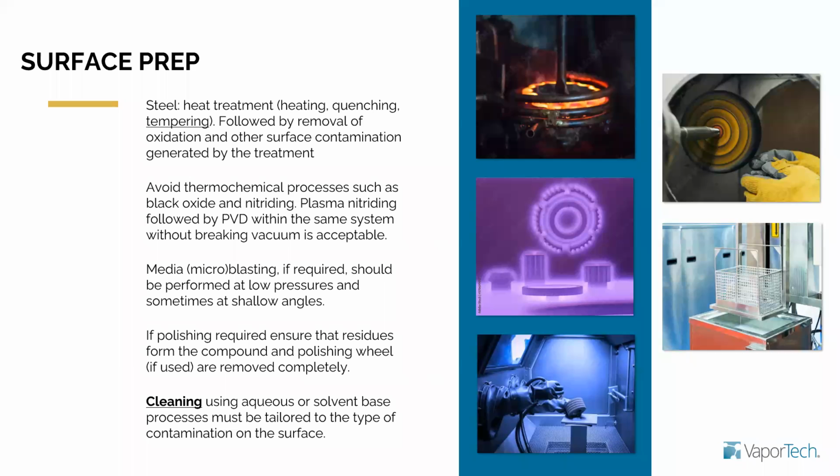Cleaning, no matter what process you're using, whether it's aqueous, water-based, or a solvent-based process, is not just selecting the right type of solvent for the type of contamination that you have, but making sure that you have all the steps accounted for in the cleaning process, meaning exposure to that solvent, but also rinsing and drying, so that you have a part with a surface that's free from contamination and ready for PVD or PECVD processing.